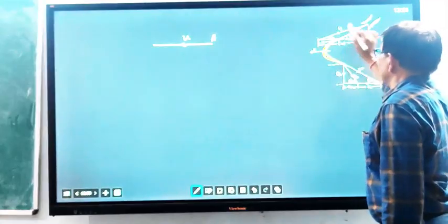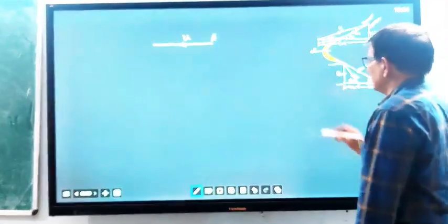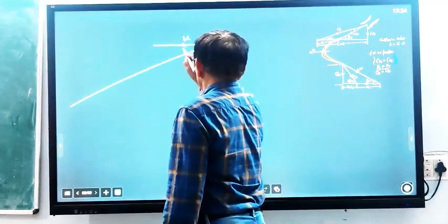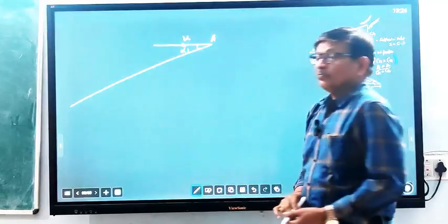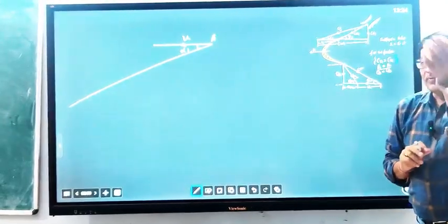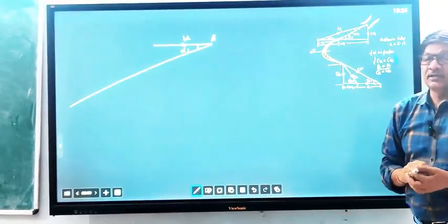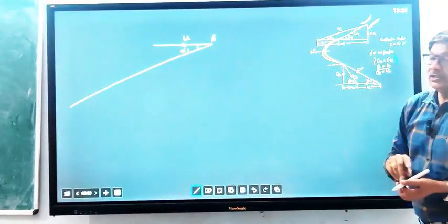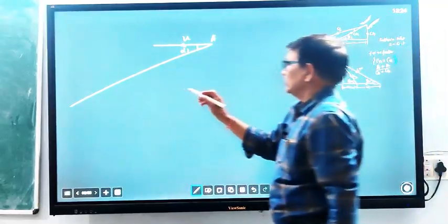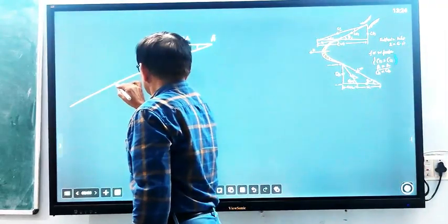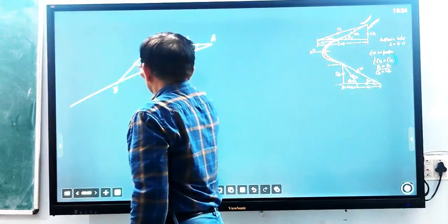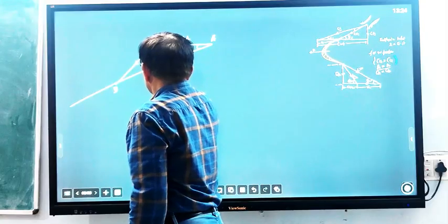First we draw U and then we draw C1. How do we draw C1? Take angle alpha 1 here, and we know the magnitude of the steam's absolute velocity C1 because it is given, how much velocity there is when steam is coming out from the nozzle. So it is given according to scale. Select a length, suppose this length, and join this one from C. Take C, and this one becomes CR1.